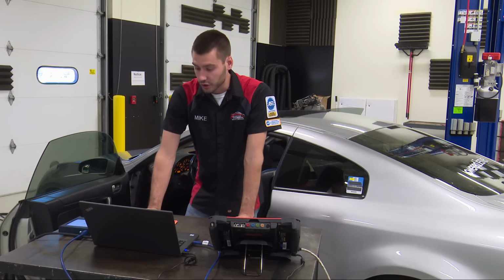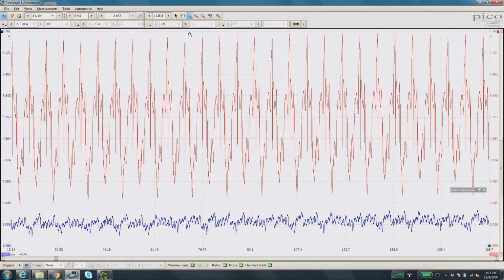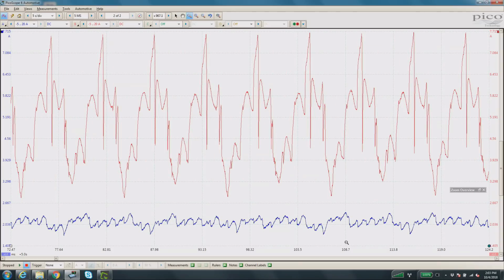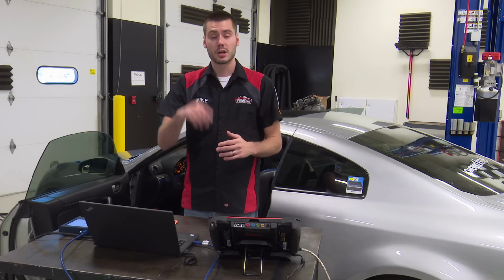But our current here is, I would say, definitely a problem. We have a significantly higher current. But let's go in even further. And those of you who have scoped fuel pumps before know where I'm going here. When we're looking at a fuel pump, we like to see a relatively consistent pattern, kind of a low amplitude for amperage up and down.